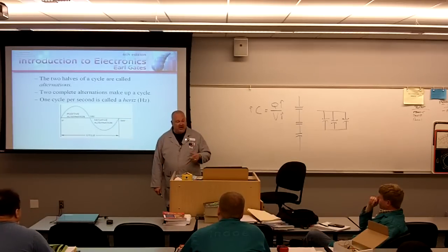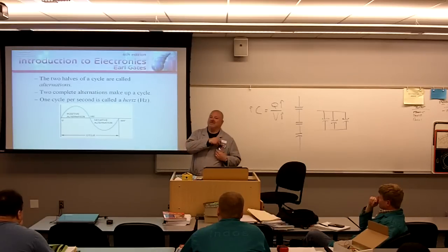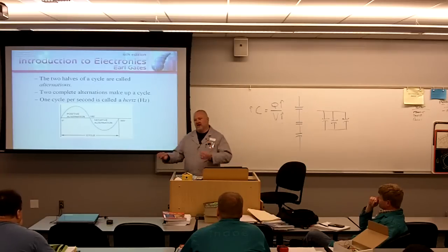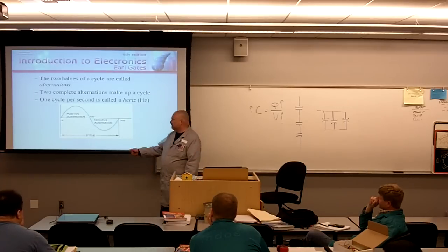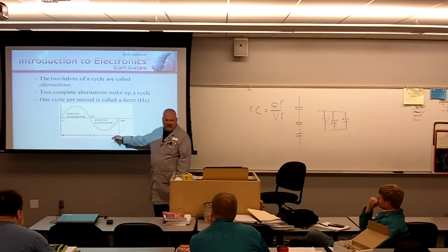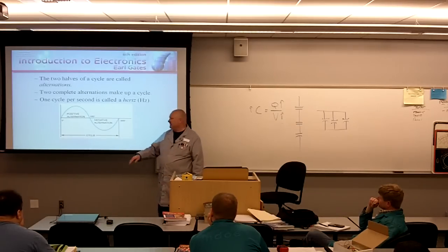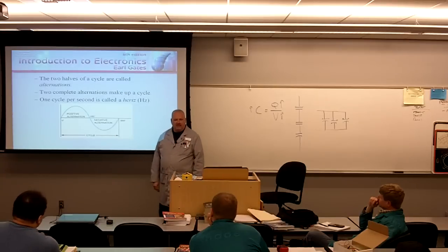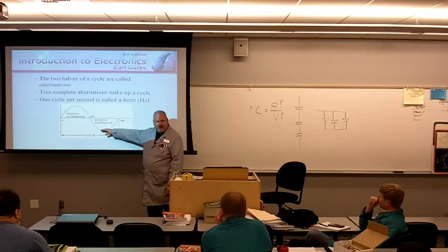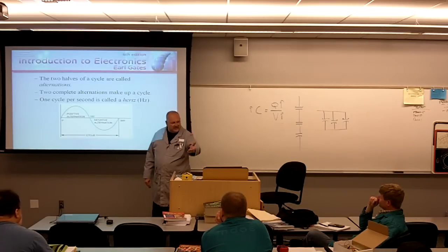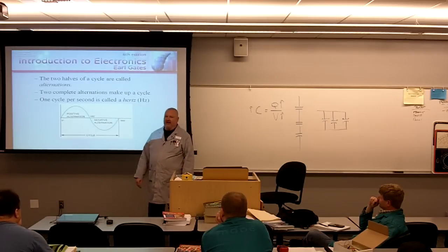Now you've got that sine key. You could predict what is known as the instantaneous voltage present at any point of a sinusoidal waveform. Isn't that the bomb? I could say, what voltage is present at 337 degrees? You could plug in sine of 337 and that gives you the percentage. You're obviously going to have to know what this peak value is. Peak multiplied by the sine of that value will give you the multiplier.